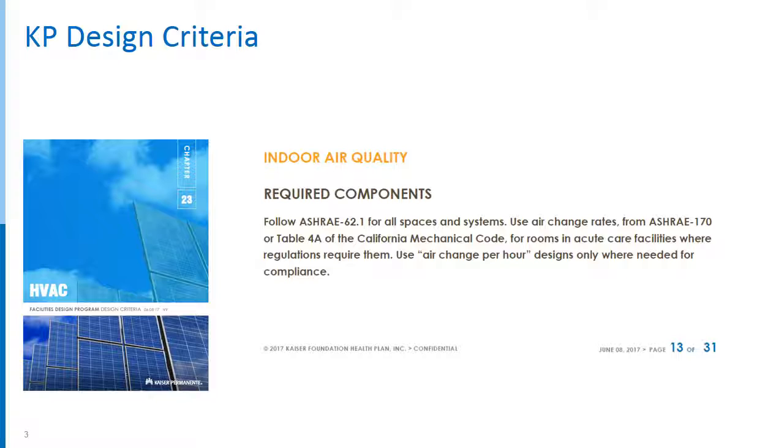And if you're doing Kaiser work, obviously, the energy targets that we have in our program are fairly aggressive, and we assume that you're not going to use air changes. There are some exceptions throughout the buildings: OR suites and scope cleaning and 797 pharmacies, isolation spaces. KP standards do call for more air there. But for most of the spaces in MOBs, exam rooms, waiting rooms, treatment rooms, things like that, we say don't do it, and you flat out won't meet our energy targets if you do.